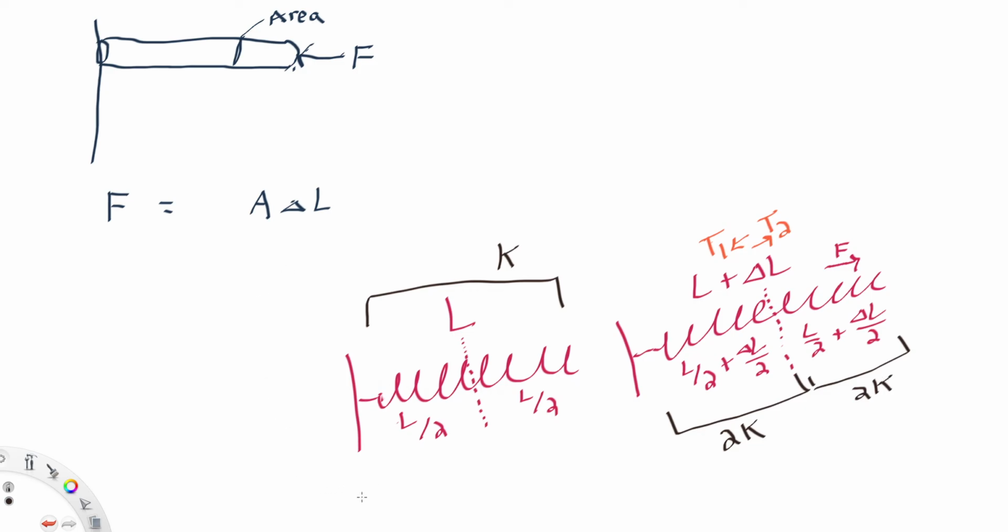And in fact, if you have a bunch of different springs, possibly with different spring constants, you can add them up to get an overall spring constant. So the overall spring constant, maybe I'll use subscript T for total, is, so you add up all of the K's of the individual springs in reciprocal, and once you've added up the reciprocals, you take the reciprocal.